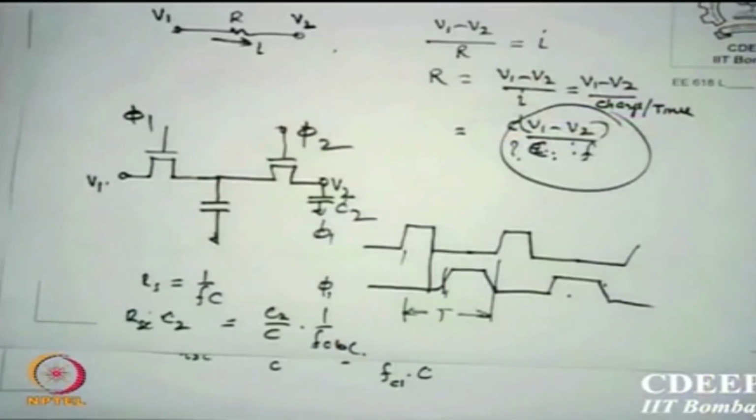It's partly digital because switches are there, and that is where the problem started. Before we quit, no reason to explain, but these switches are not ideal. Now they create a hell of an issue. One problem, which everyone should know whether it is a digital or analog circuit: when the switch is on, there is a charge in the channel.